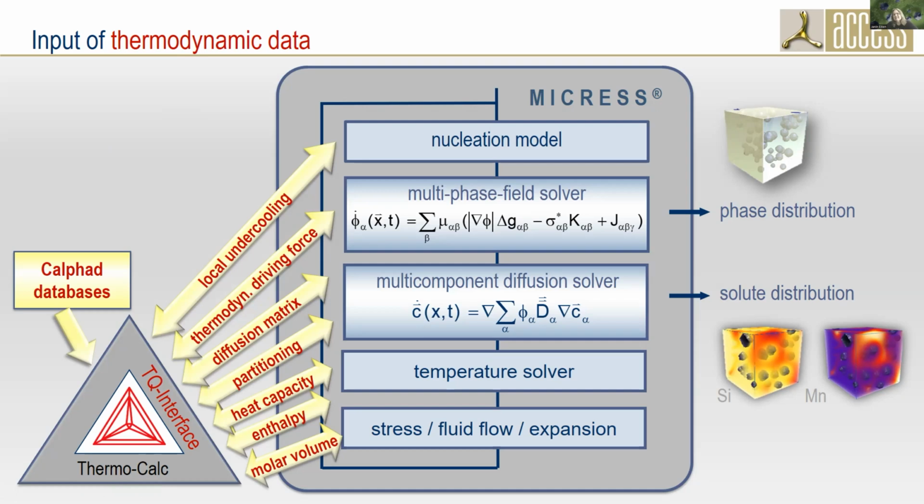But yes, even if you go to 100 times 100 times 100, it ends up with really large numbers, and if you just double it, then... so yeah, most of the time we try to do it as coarse as possible. But I guess it also depends on the morphology. Exactly, you do have to choose the cell spacing so that it's smaller than the critical length scales and the diffusion lengths.